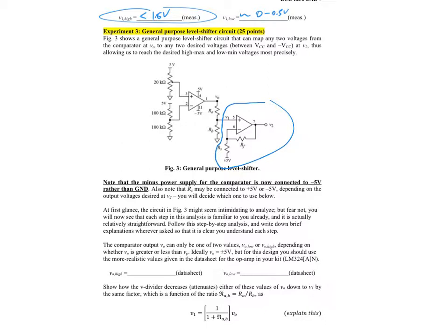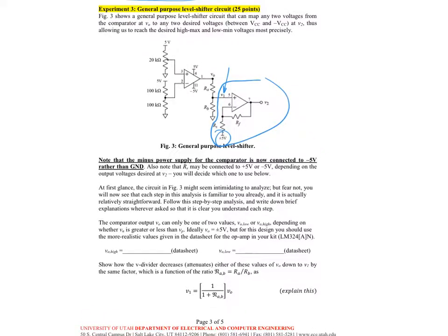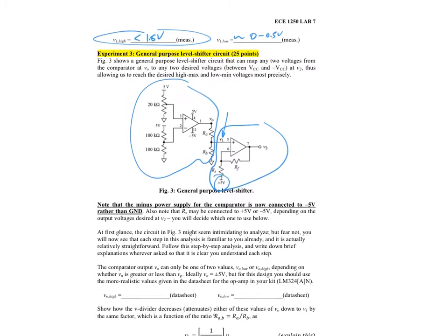So we're taking V1 onto the positive input, so it's going to see a positive gain. And then plus minus 5 volts here is on the negative side, so it's on the inverting side, which means it's going to see an inverting gain. And it's as simple as taking what you've already done with this part. You've already done the divider up here.